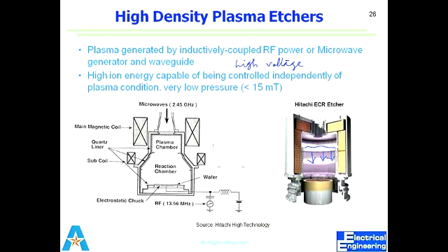But if I have a very thin film that needs to be etched, I don't care about the etch rate. I say okay, the low energy density is fine because I don't want my surface to be damaged, and secondly I want very good control on the surface. So it depends on the thickness of the film, not the aspect ratio, right? You can have a high aspect ratio, but a very thin film covering it. If I want to etch that film, then I would go for a low density process rather than the high density one.